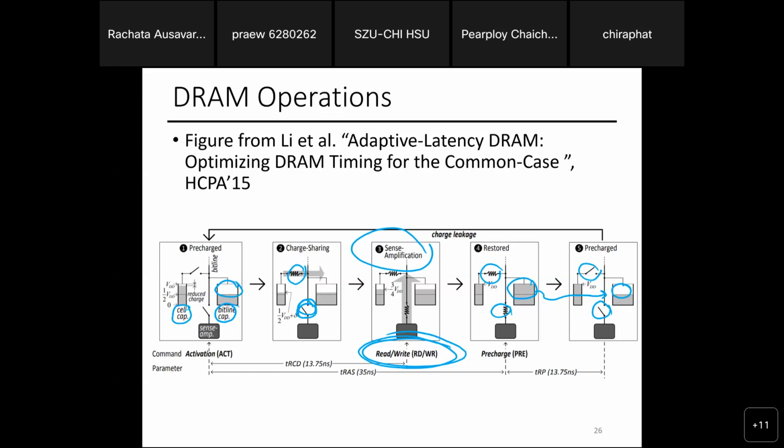When you have the DRAM operation, that's a shared data bus. So in the case of the write, the shared data bus will be the data you want to write, with the correct value. The sense amp would basically amplify these into the DRAM instead of reading something from here out to the data bus. So this is just reading from somewhere. Yeah, just copying.